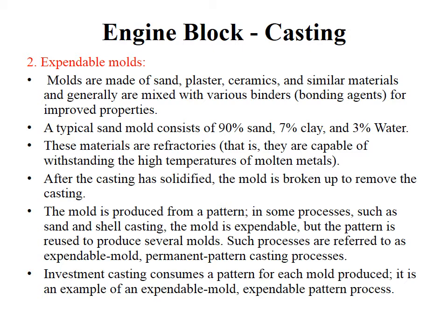So pattern is nothing but the component which basically has the shape. It's basically a replica or a prototype of the casting component which you need. That you call as pattern. So surrounding the pattern, what you have is nothing but the mold. If it can be destroyed, it is an expendable mold. And one example for expendable mold, expendable pattern process is investment casting.